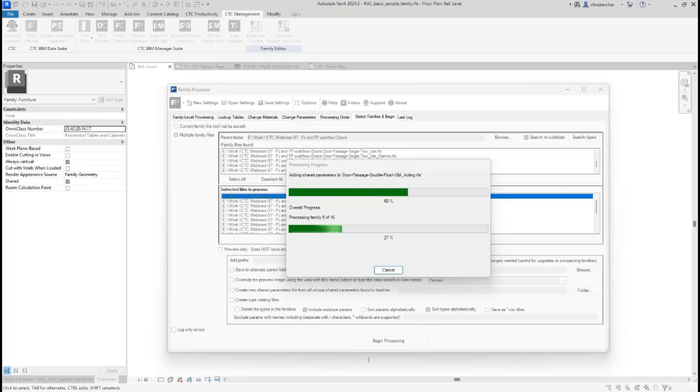If Parameter Jammer is not showing you the parameters from the schedule, then chances are they're not the parameters in your parameter file. And so that's where I would start. And if you need to use a schedule parameter resolver to clean up your schedule to use those parameters without blowing up your formatting, go for it.